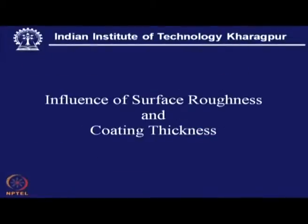As such, the material can be a very good tribological material having one of the best tribological properties. However, since it is not very smooth, this surface roughness can have an overriding influence in escalating the friction to a very high value. So, the chemical inertness of the material will become less significant, and more important will become the roughness of the coating. And at least one can understand the frictional aspect, the wear of the component, the power requirement to drive the device or the machine with all those coated components.